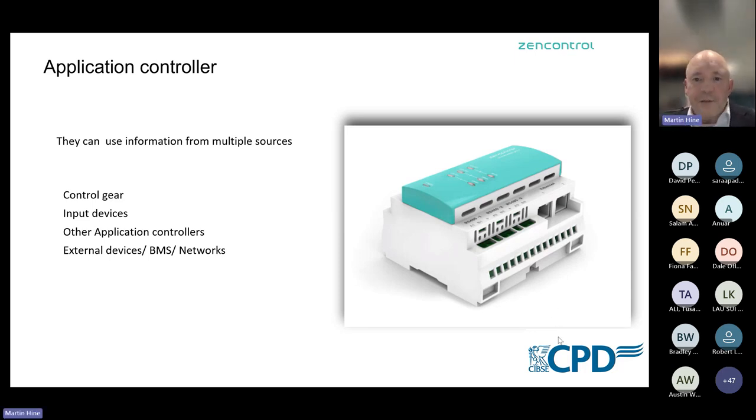So the communication interface in the application controller, between the DALI 2 network system and the external systems, as I said, connects via the Ethernet ports attached to the application controller, and these will then go off to the BMS and other third-party applications if required.